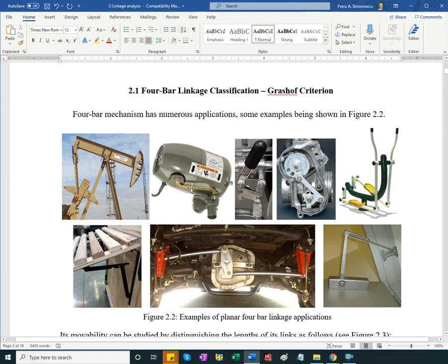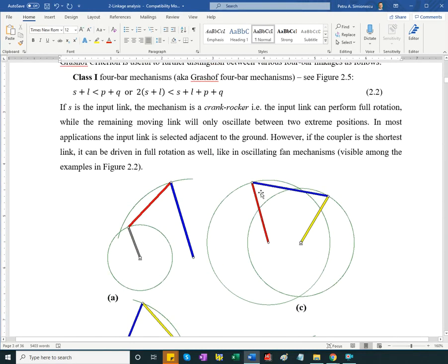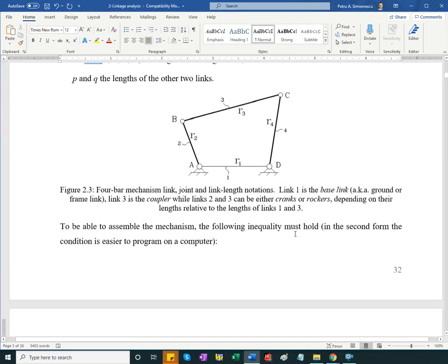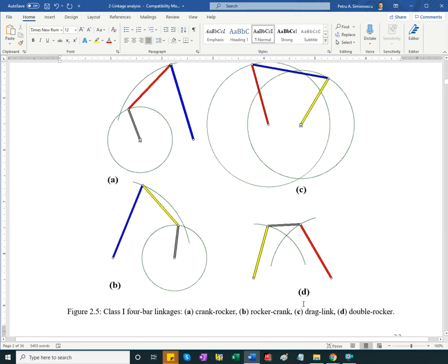So motion from the electric motor rotor is reduced to a few tens of RPMs. It's causing that floating shortest link, the coupler of the 4-bar, to rotate. One is the fan body, and then the other one is the visible link in this picture. And so that's how you get the oscillating fan working.